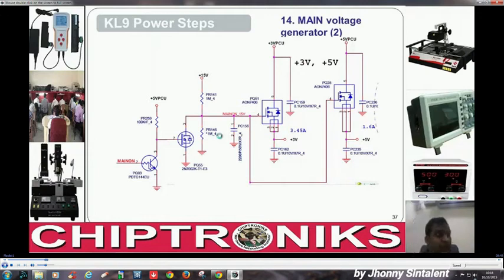Well, it seems a very good question, and of course you can tell. By seeing a notebook motherboard, we can have a 98% idea of how it will power on, and we are going to develop that strategy and concept. We don't always have to look through the schematic diagram to get an idea of the power sequence. We only have to go through the schematic diagram to see the specific resistors, capacitors, and pin numbers, not the sequence.